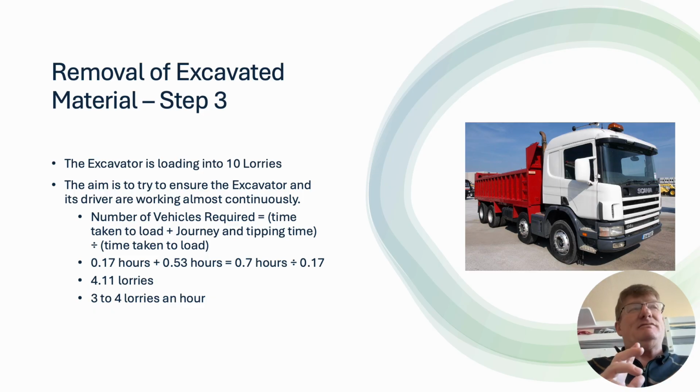It would depend on how fast we go. It depends on whether it's built up traffic or it's in a rural area. It depends on how far the tip is away. And then obviously you've got to maneuver whilst you're at the tip before you can tip it. So we're saying it takes about 25 minutes by the time you get to the tip, maneuver, tip it. It takes around 0.53 of an hour. And then we divide it by the time taken to load, which is 0.17.